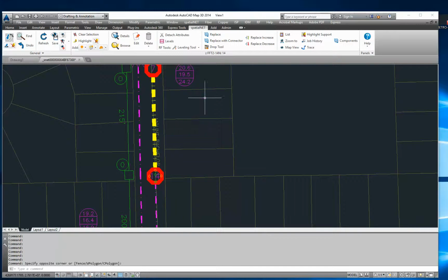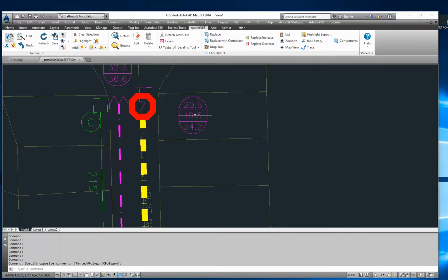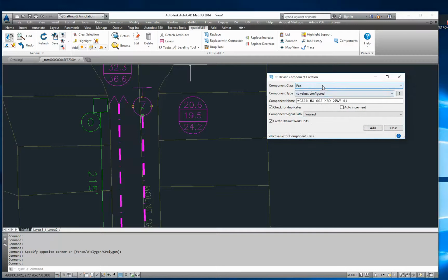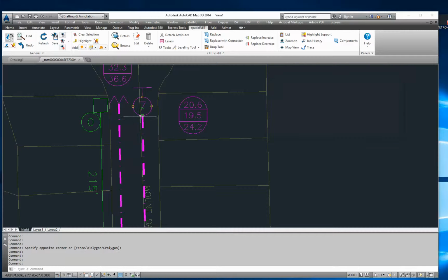And so now we have a 20 over 24, which is a little bit closer to what we want, and there is still that 3.6 dB tilt. So with the 3.6 dB tilt, go and hit clear to clear this highlight. We're going to select that, and we're going to basically add RF component. And what we're going to do is add an equalizer, and oh, looks like there is nothing configured for this spec, so I guess we're just going to leave it as is.